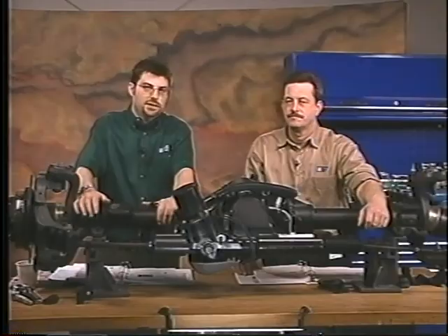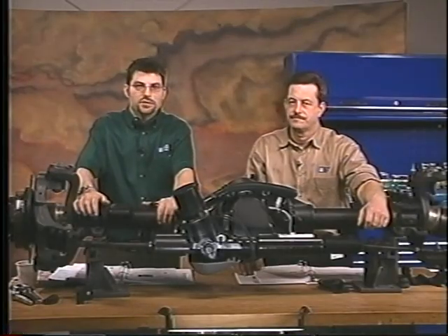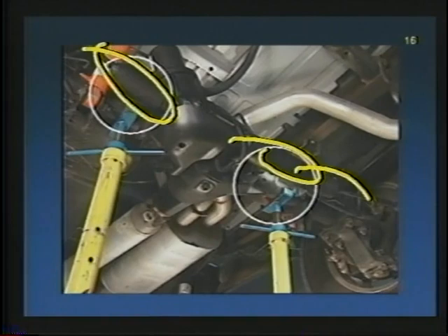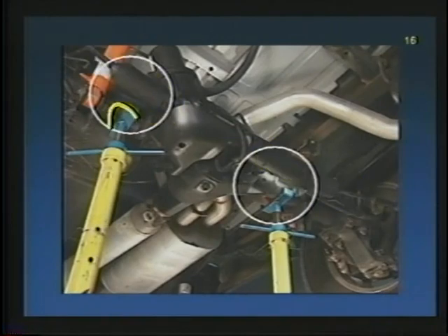Well, this leads us to a tech tip we have for you on page 1-7. It has to do with lifting and jacking the vehicle. Now, a couple of things to keep in mind. If you're using one of those old school twin post in-ground hoists, where you have that cradle that comes up and grabs the rear axle, you have to make sure you don't contact the skid plate. You have to make sure you don't lift the vehicle by the actuator or the inner tie rods. You have to make sure you contact it by the axle housing itself.